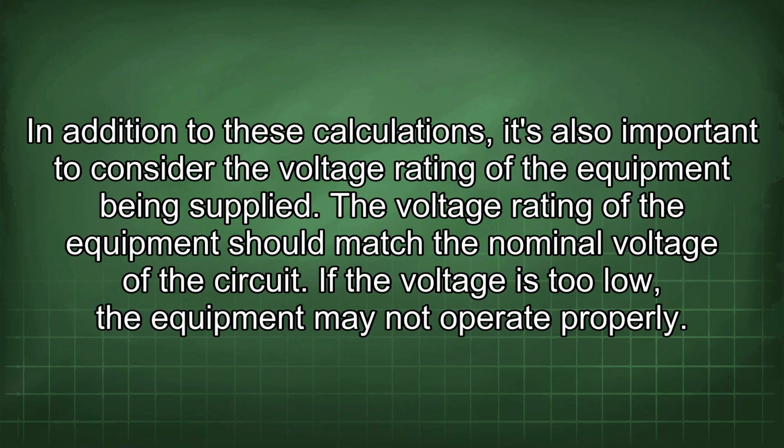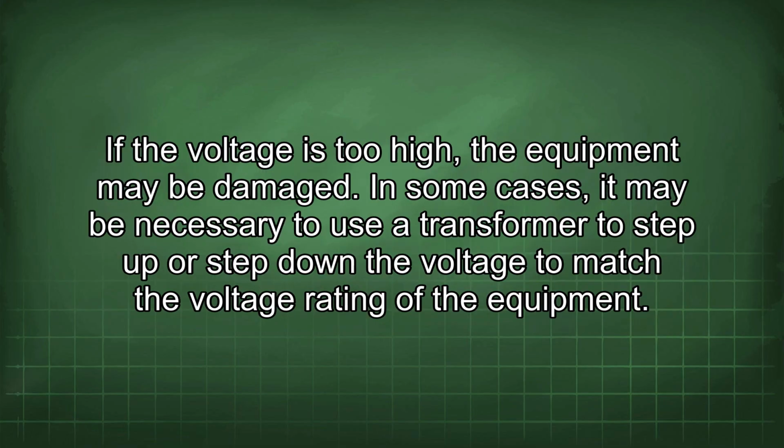In addition to these calculations, it's also important to consider the voltage rating of the equipment being supplied. The voltage rating of the equipment should match the nominal voltage of the circuit. If the voltage is too low, the equipment may not operate properly. If the voltage is too high, the equipment may be damaged. In some cases, it may be necessary to use a transformer to step up or step down the voltage to match the voltage rating of the equipment.